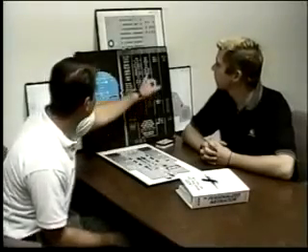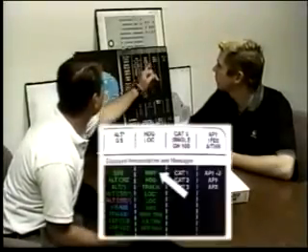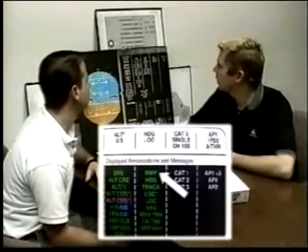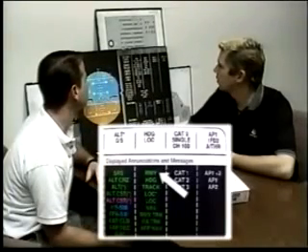On your lateral modes, the third column, what does runway indicate? Runway indicates that you are, during takeoff, on a runway with a localizer, and you have that runway selected in the MCDU. From takeoff roll to 30 feet, it'll indicate that it's giving you guidance off of the runway localizer. So would you get this symbol as well? Yes, if you're doing a takeoff out of National or out of Dulles, out of any runway that's got a localizer that we've selected, we'll get runway.